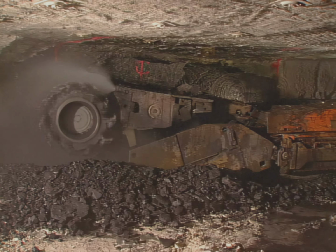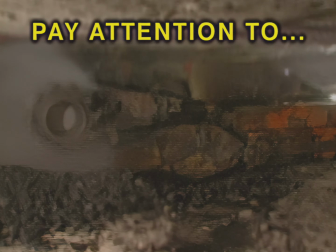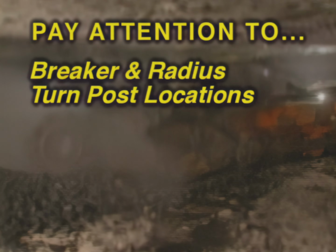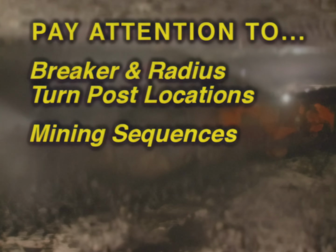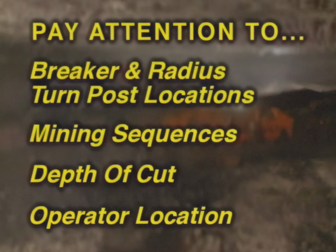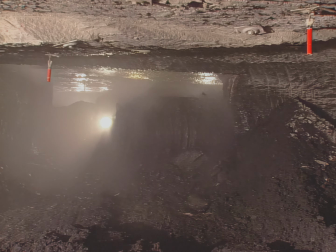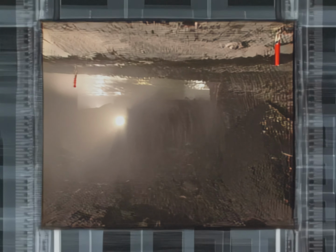Follow the roof rib control plan at all times. Pay attention to the safety provisions in the plan that cover breaker and radius turn post locations, mining sequences, depth of cut, and operator location. It's especially important to do so when mining the last lift or final push.